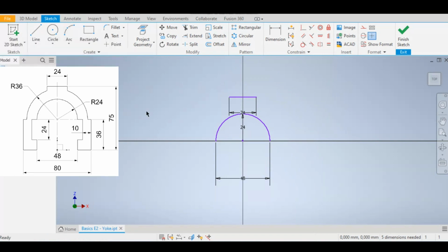and then for the second option I'm going to select my arc. So from the arc we know we've got a radius of 36 for our arc, so my X value is then going to be 36, where my Y value is going to be 0 as it is on our X axis.